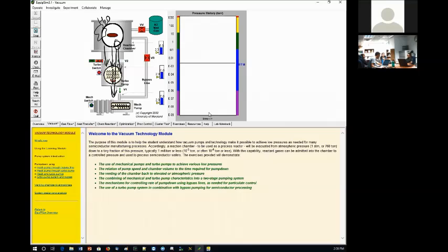Okay, so that will make something much higher, because the partial pressure of water vapor will now be much higher than 20 torr. What's going to happen? It will condense. Does that make sense? Because you have still left 20 torr there, but the overall chamber pressure is lower than 760 because you're taking it very quickly without checking what you're getting out. So in that case, the condensed water will condense on the walls. And that's a very critical thing.